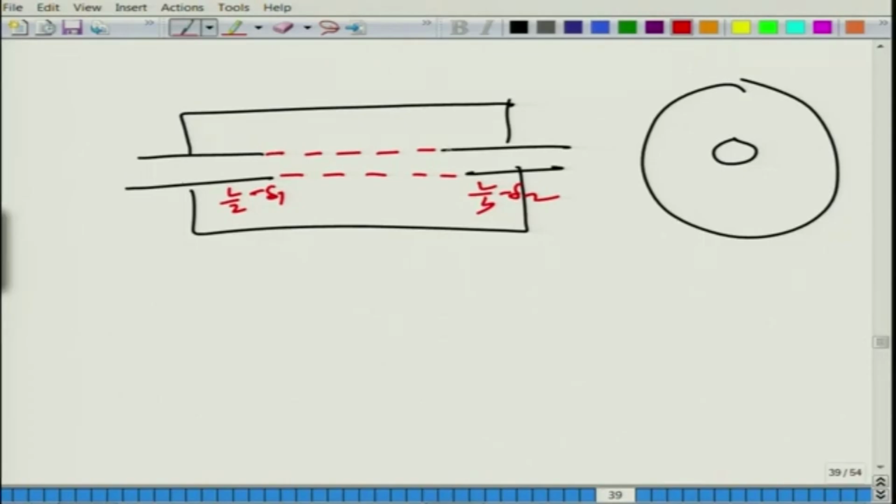So, basically what you need to do is connect the inlet and outlet pipe with a perforated bridge. We connect that, and so we do not allow the flow to expand. We never allow the flow to expand, it just goes away, and it interacts with the annular cavity. The waves interact with the annular cavity and they have resonances here and resonances here, but the flow itself just goes smoothly. So, there will be a minimum pressure drop, and because there will be no free shear layers formed, there will be no vortices formed in the wake which would otherwise form if the perforated bridge were not there. So, the flow induced noise, the counterproductive noise, will not be there.